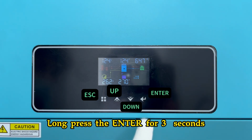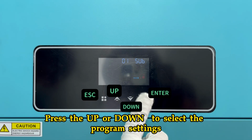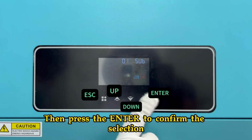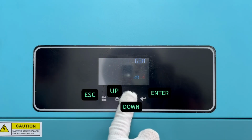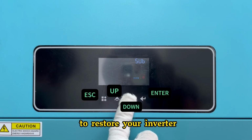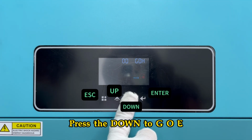Long press the enter for 3 seconds. Enter setup mode. Press the up or down to select the program settings. Then press the enter to confirm the selection, or press the ESC to return. To restore your inverter, press the enter to settings. Press the down to GOE.